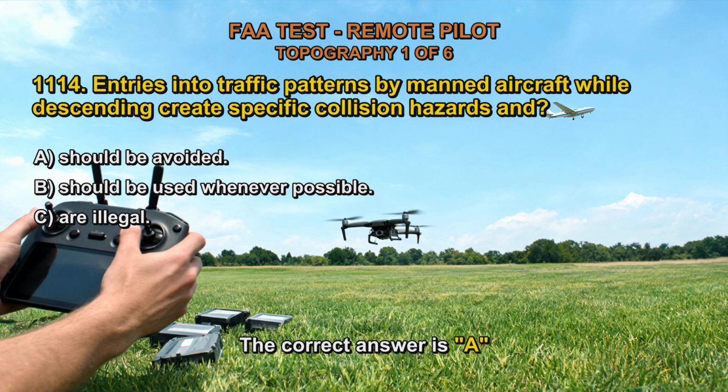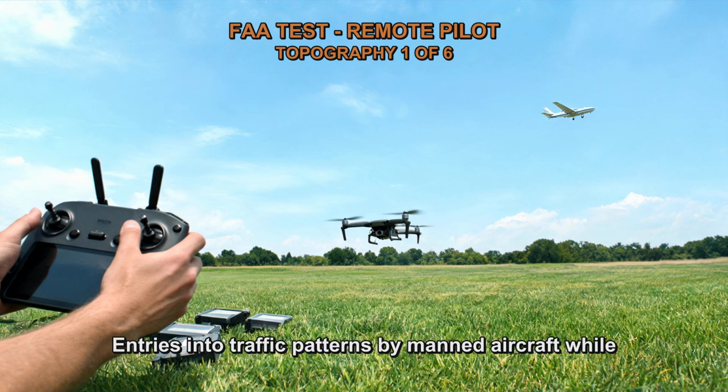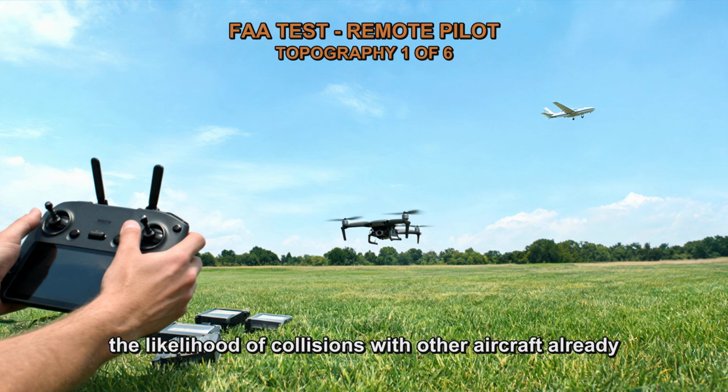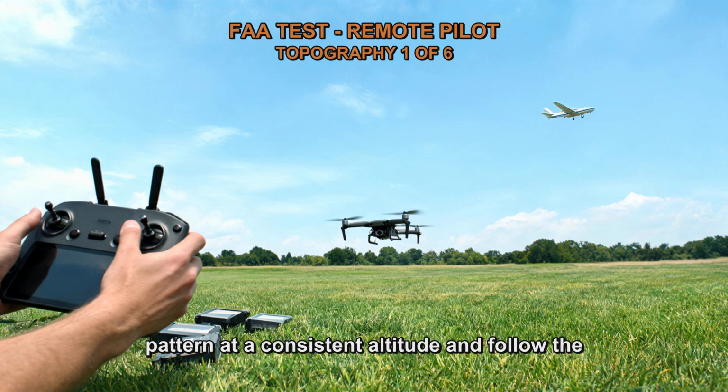The correct answer is A. Entries into traffic patterns by manned aircraft while descending create specific collision hazards, as they increase the likelihood of collisions with other aircraft already in the pattern. It is safer for aircraft to enter the pattern at a consistent altitude and follow the established traffic pattern procedures.